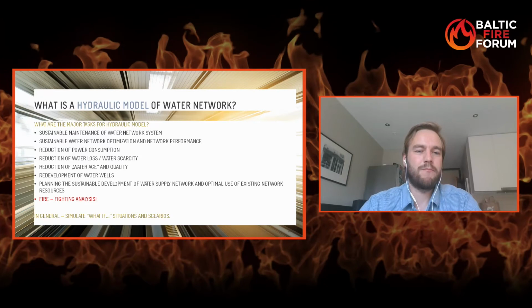It also helps in planning and sustainable development of water supply networks and optimal use of existing network resources. And the last, but not least, fires: how to analyze fires, how to calculate fire water flows, and so on. Today I will talk about that. In a very general sense, the model has to simulate situations and give you answers to what if something goes wrong. For example, you have power losses in wells or pumping stations, or you have to close some parts of your network system, and so on.